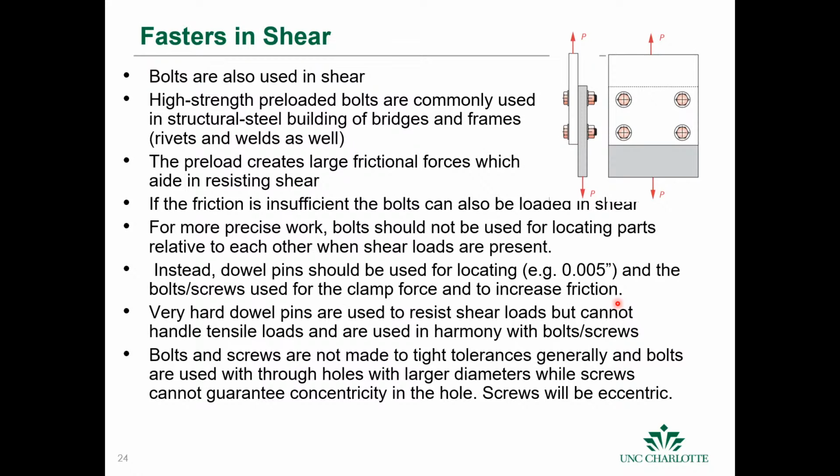So that covers joint stiffness and bolt preload, and the effects of installing it with a torque wrench or other application. The next thing that we have to talk about is what happens when the fasteners are in shear, which is often the case.